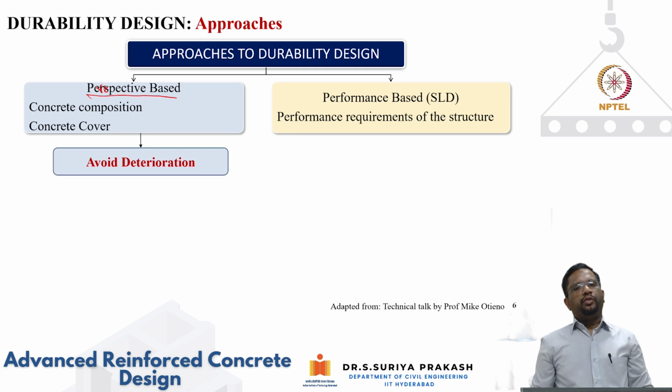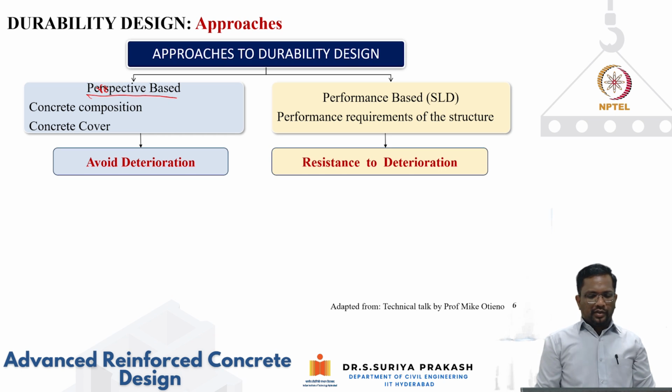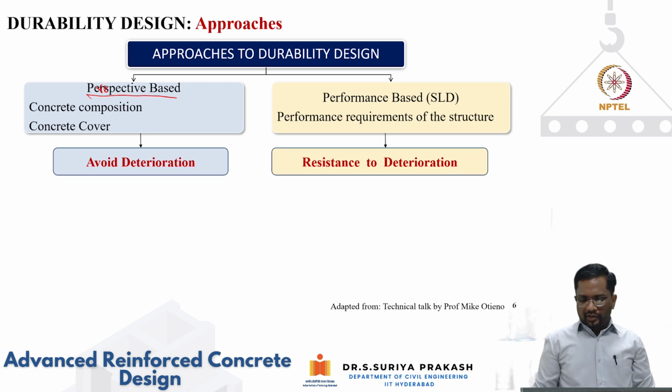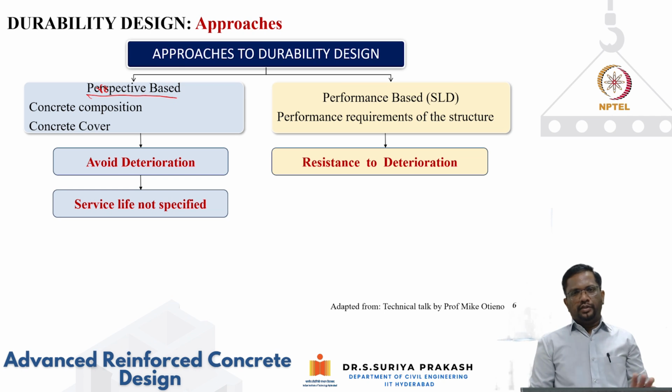The other one is performance based. It depends upon the performance requirement of the structure. Here the approach is to avoid deterioration. In performance based durability design, or serviceability for durability, we design resistance to tackle the deterioration. In the prescriptive approach the service life is not really specified, it is assumed.